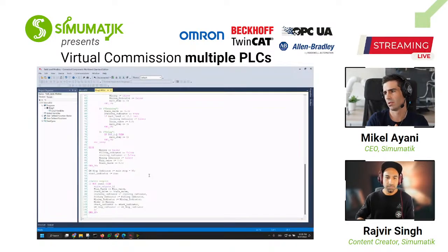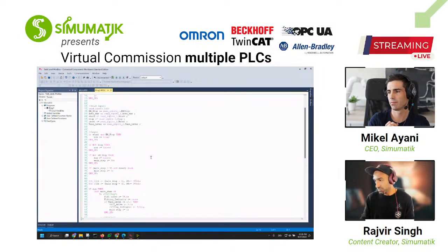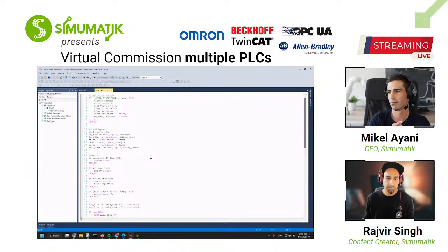Are you using PID or not? No, just simple. Here in this example with the PLC, I'm not using PID, but the next example with Node-RED, I'm using PID. I'm going to show you the setpoint and feedback as well. But for sure, we can also write PID code in any PLC you want.